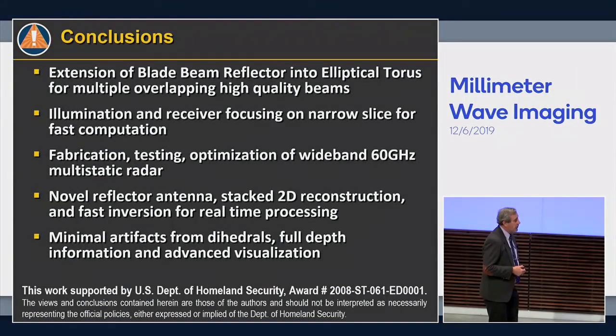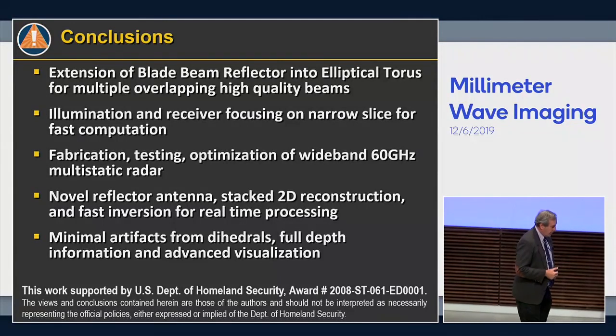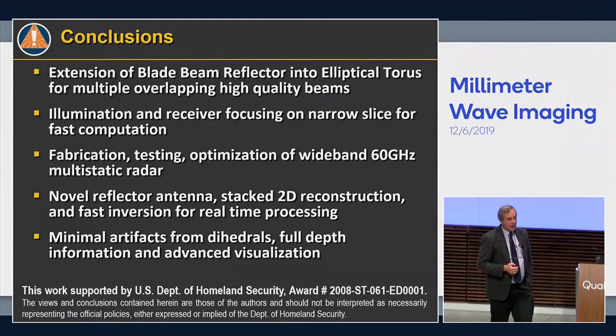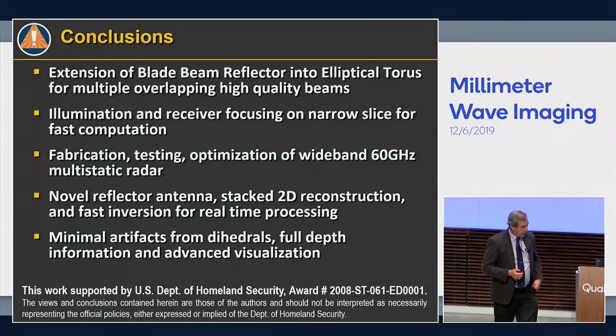We've built and tested this at 60 gigahertz. We've been using custom chips by ADI, inexpensive chips of the order of $100 a channel. These are not designed as radars, but we've configured them as such by using a separated radio receiver and transmitter, a 60 gigahertz system with separate local oscillator synchronization clocks. The idea is that if you run a reference line as well as a line through the air, the amplitude and delay associated with the line through the air, in effect, becomes a radar signal. And as long as you process that intelligently, you get a nice radar using hardware that costs what a radio costs, $100 a channel, as opposed to, when we first started this, about $250,000 for a radar channel.